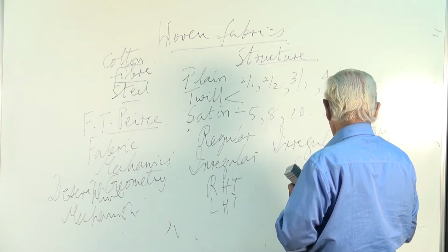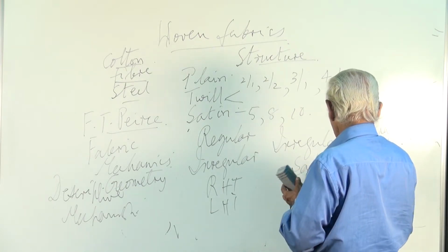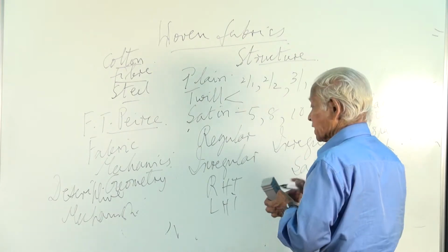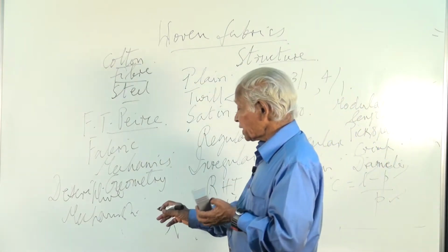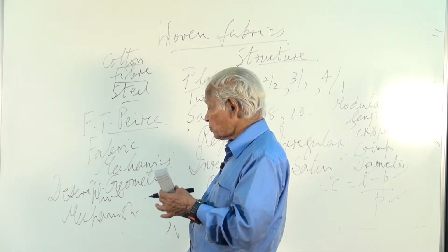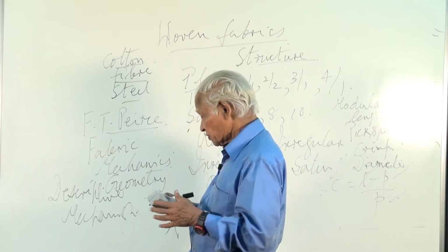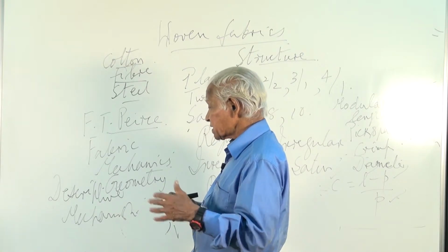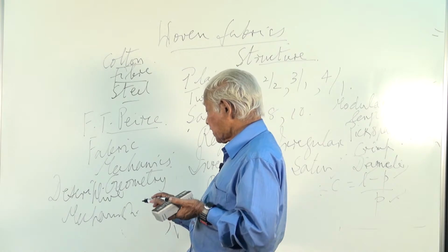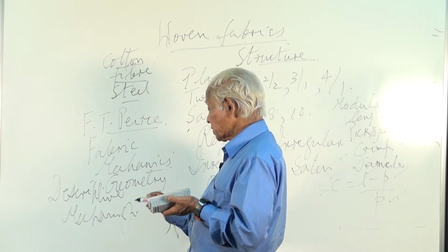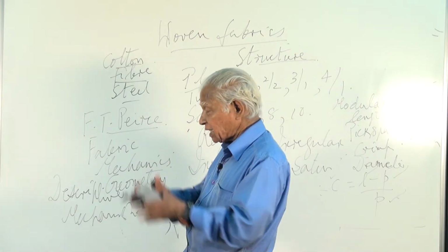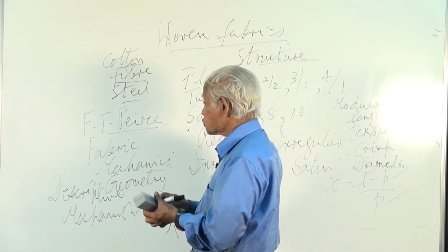Thickness can be calculated, and crimp can be calculated. From the crimp and the pick spacing, the modular length can be calculated. But in the mechanistic model, it is very useful for predicting the mechanical properties of the fabric, whereas the descriptive model has got certain limitations, and it is very difficult to find where this fabric mechanics changes from the descriptive model to the mechanistic model, or that line which divides these two.